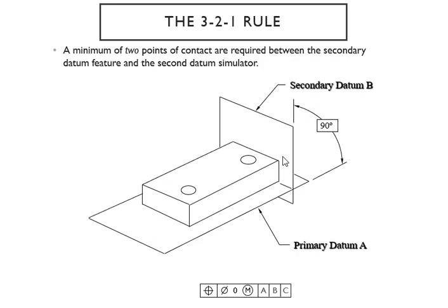Sometimes you have an issue trying to locate these points, and you think so hard. Don't think so hard. It's just right there on that plane, connected to that part on that surface. You can choose any 2 points. I usually say in contact, because this plane and that plane are in contact, so I just take that as 1 point. And another one is going to come with a tertiary datum, so that's 2 points, and the surface is set with the 3rd one, so that's how I take it for the primary.